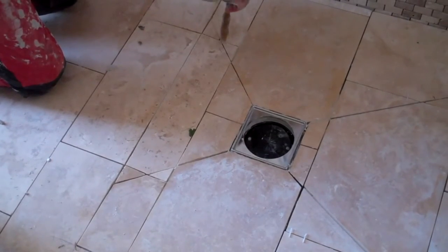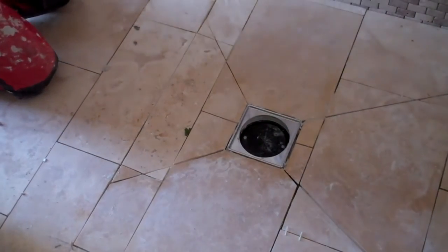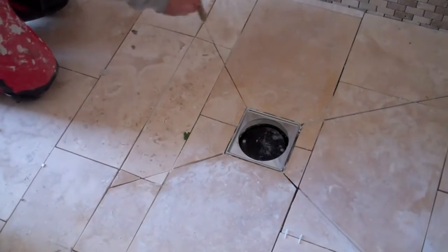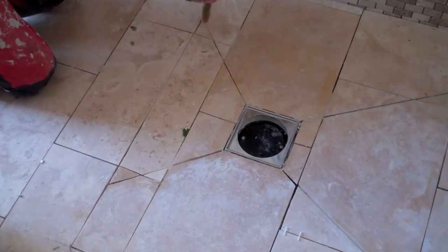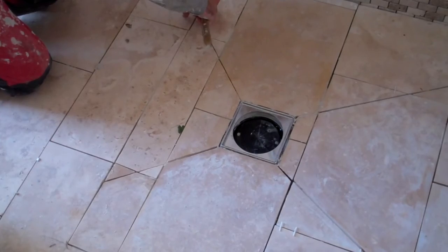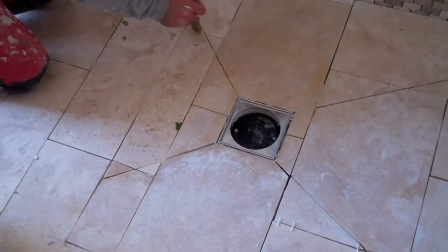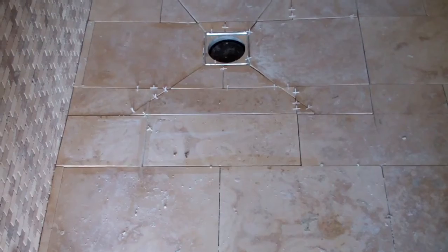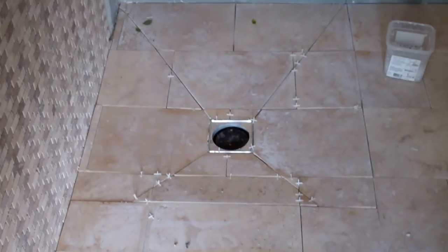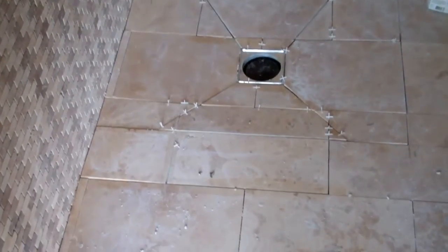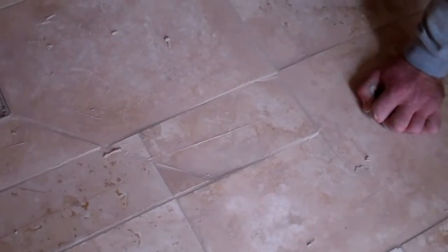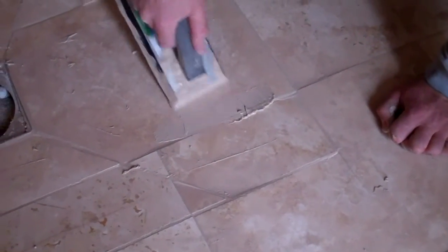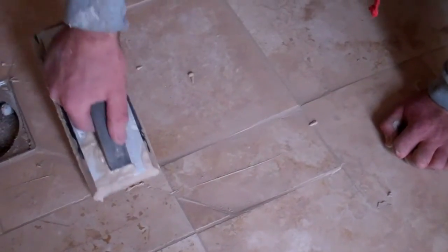If any battens are tacked to the walls for temporary supporting of the wall tiles, then the nail holes must be filled with aquaproof compound. When all the tiles are cut and bedded down, insert the tile set frame into the tile adhesive so that the top of the frame is level with the adjoining tiles. Waterproof tile grout is applied exactly as normal, filling all gaps between the tiles.